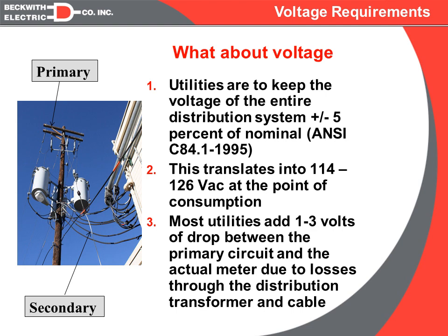Now in general, a voltage drop is going to be reduced across the entire system because when you transmit current, it has to go through the system to get from the generator to the consumer, and that system has impedance, mainly in the forms of the cable itself carrying the current, and then the transformers throughout the system that are used to either step up or step down the voltage. And these cables and transformers have impedances. These impedances, by definition,